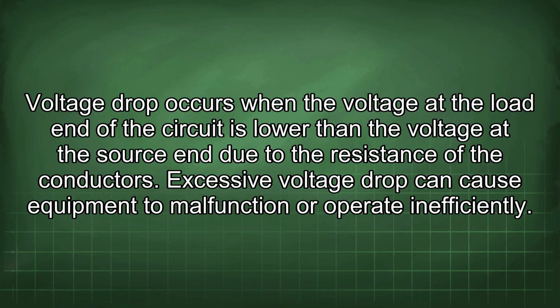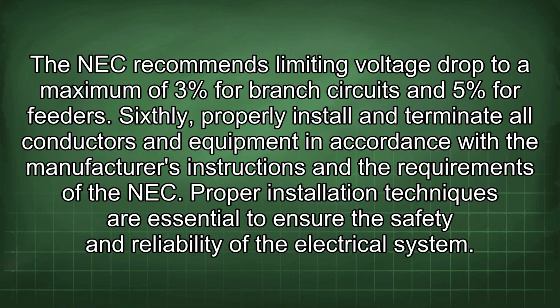Excessive voltage drop can cause equipment to malfunction or operate inefficiently. The NEC recommends limiting voltage drop to a maximum of 3% for branch circuits and 5% for feeders. Sixthly, properly install and terminate all conductors and equipment in accordance with the manufacturer's instructions and the requirements of the